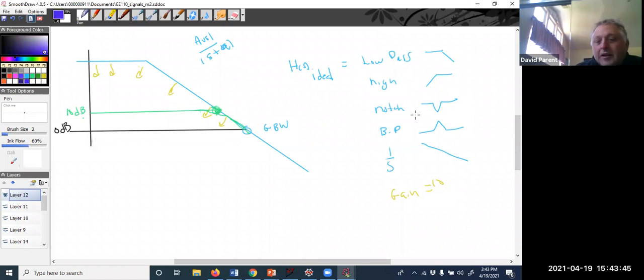If I have an integrator, which is a line going downwards, I'm drawing it where it works somewhere, right? Because if I draw this purple line over here, it doesn't work anywhere. Notice in this case, it's intersecting at the low frequency because for integrators the magnitude goes to infinity at DC.